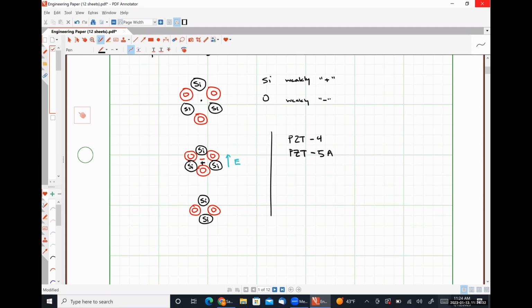You do have to be careful though, because much like in magnets, if you were to increase the temperature of the material beyond its Curie temperature, it would lose that residual magnetization, effectively resetting the grain boundaries and all that kind of good stuff. So that process is what's called poling, P-O-L-I-N-G, because it's establishing a net dipole moment in the crystal. And that is something that's very common in man-made ceramic piezoelectric materials.